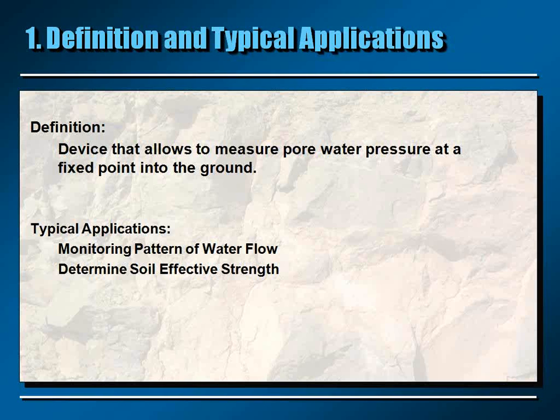First, what is a piezometer? A piezometer is a device that allows us to measure the pore water pressure at a fixed point in the ground. It is really important to understand that the piezometer must measure the water pressure at a certain elevation in the ground and should not be affected by what's happening above or below.